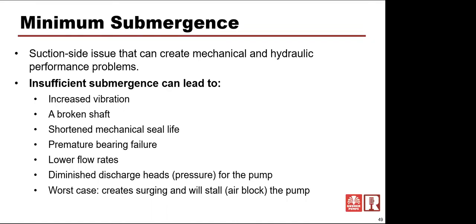So what happens is that volume goes up and down as it goes through the pump, and that causes vibration inside that pump, on the shaft, on the impeller, and it causes vibration to the seal, which can cause seal failure. So if you have a fair amount of air coming into the system, because of the vibration increase, you can create seal failures or bearing failures prematurely. You may have, again, a shortened mechanical seal life, premature bearing failure. You're going to have lower flow rates. You're going to have certainly diminished pressures.